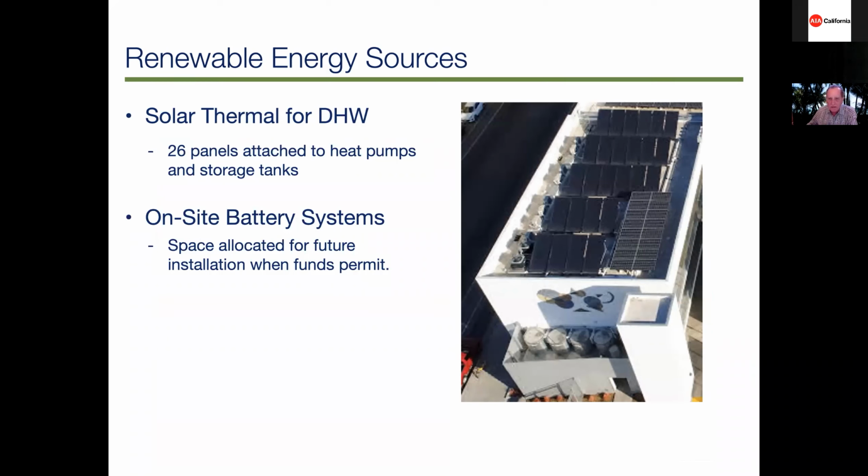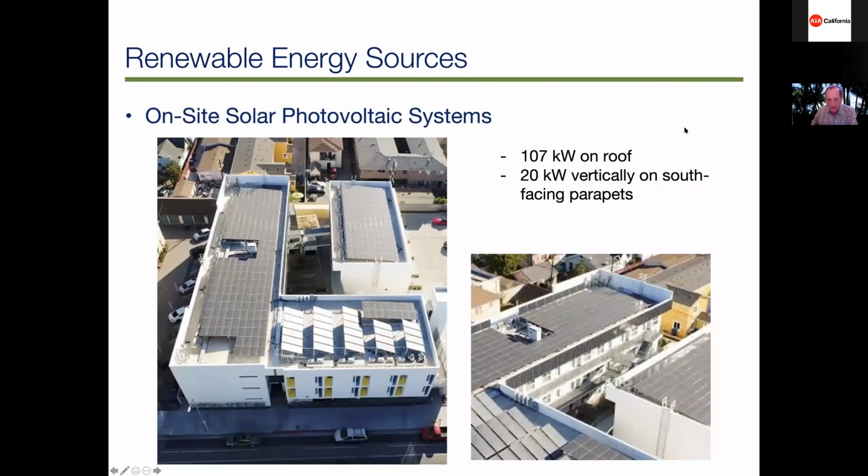So they really had to squeeze it. Let me go back one slide. In the lower right-hand corner, I'll move my arrow over there. What they found when they did analysis is that the electric power supplied by the PV system was not going to meet the calculated load. So that was in the modeling. And so they looked for a place to put more panels. And you can see right here, they attached them to the parapet on the south side. And there's a few over here on the inside of the parapet. And they've maxed out where there is solar arrays.